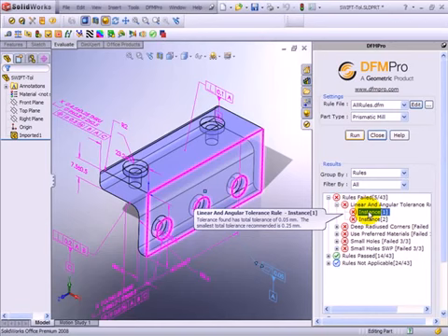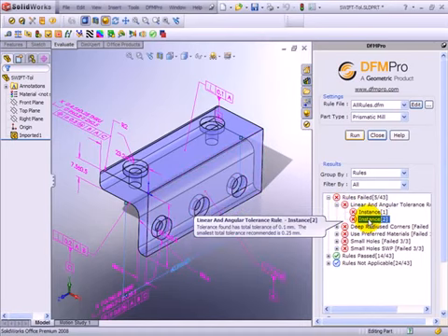Now the design engineer has two choices. Either he goes for the output which matches the manufacturing process capability, or if this tolerance is a design level constraint, then he asks manufacturing to go to a more precise shop where this part can probably be manufactured. But in this case it becomes a conscious decision rather than an uninformed decision. I can also click on the second instance and see the second dimension value where the tolerance is tighter than the process capability.